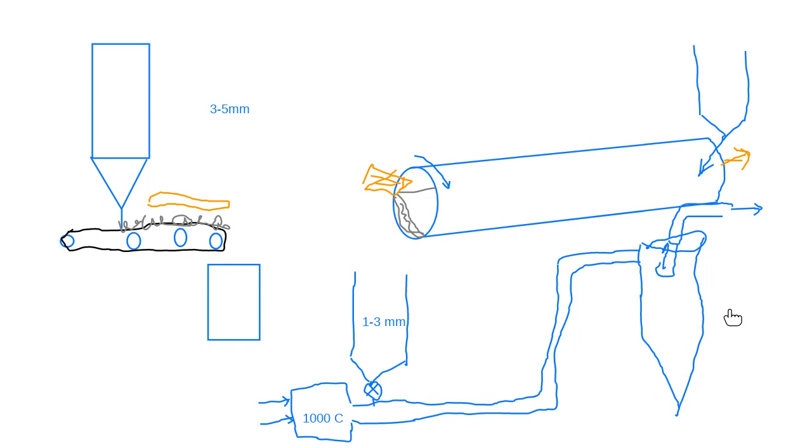Well, the power won't go out. I mean, essentially, you've got a burner here. So if the power goes out, your burner will probably stop, and you'll shut off both your air and your fuel, and you'd stop the rotary valve from going. So I don't think it would be a problem, any blockages in that respect. Even if some wet stuff did fall down, when you start up again, it will dry out, and you're going to design this pneumatic line with high velocities that will push it out.